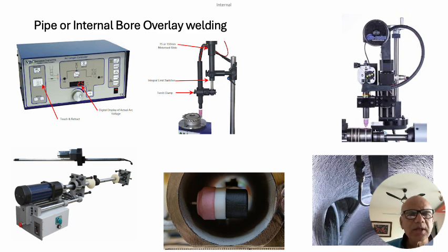So you need to take an extended length of a torch plus a wire feeding attachment that will go towards the end of it, and the whole thing has to really work with very limited access or no access, as we do a boring inside machining operation, where you don't come to know what is the finish you are getting, and all your settings are adjusted from the external parameters or the knobs you have on the machine.